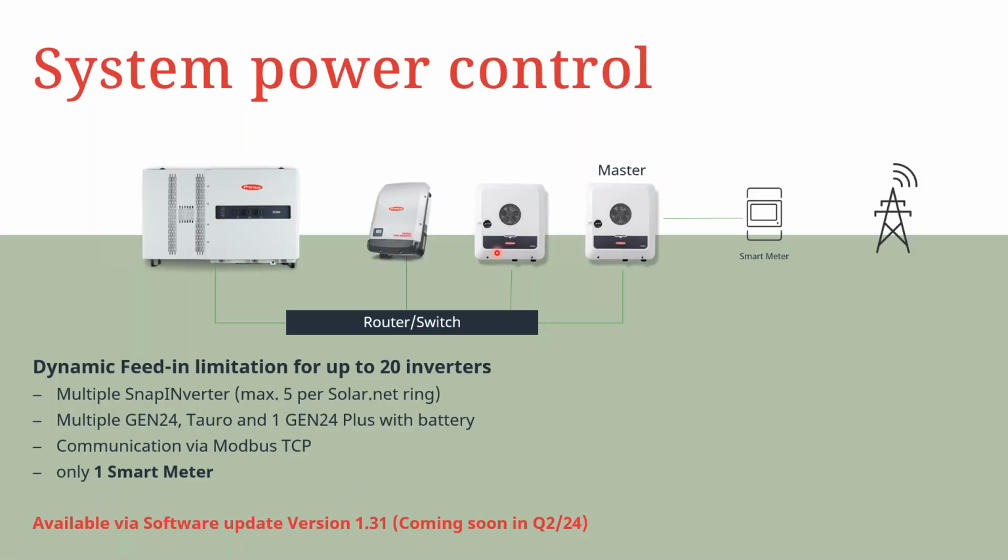So let's have a broader look at it. Using the illustration in the previous slide, this is basically a simplification of what I have mentioned earlier. With the help of a router switch, you can interconnect all the inverters in a star topology, and then the master is the main device that controls whatever output is coming from the other inverters via this star topology communication line.